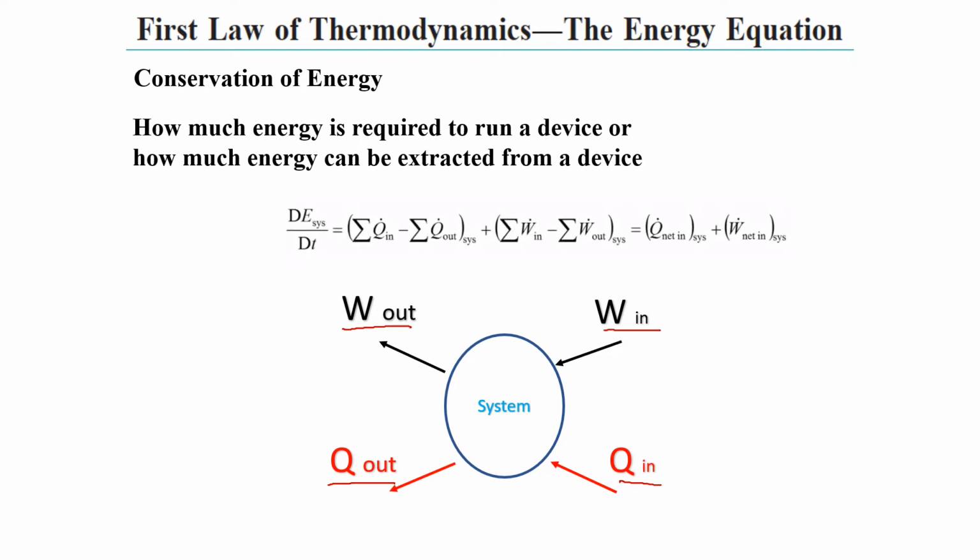So just to put it in equation form, and this is our left hand side of our Reynolds transport theorem, because you can see we are now talking about the total change with respect to time in the energy of a system. That total change with respect to time in the energy of the system will be equated to those two terms, that is the heat in minus heat out for the system plus the work done on the system or the work done by the system.